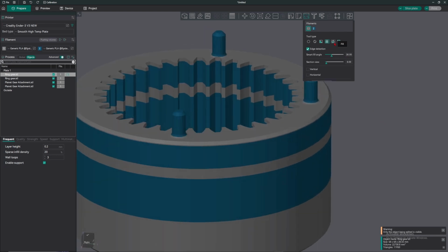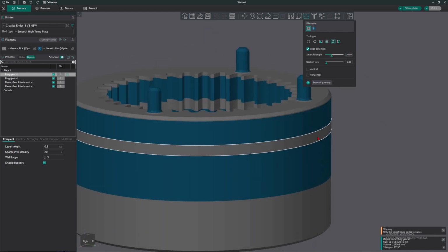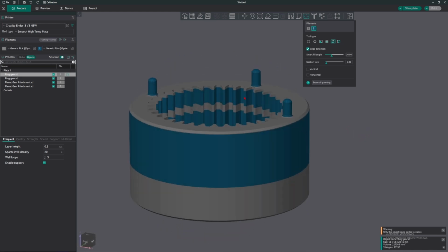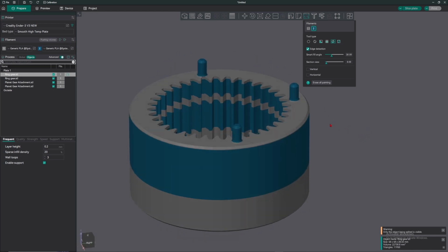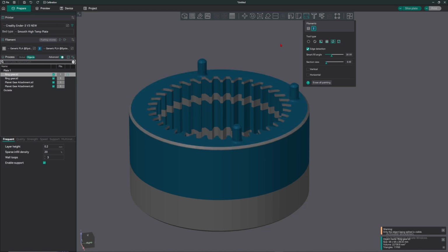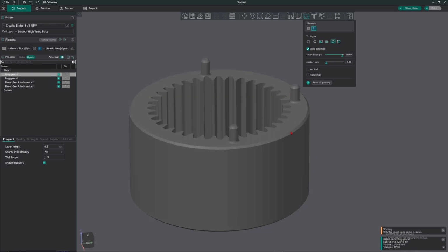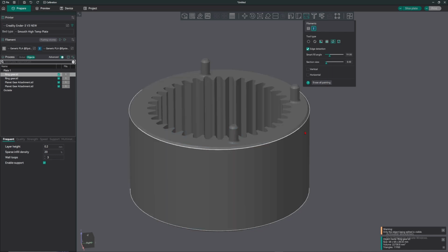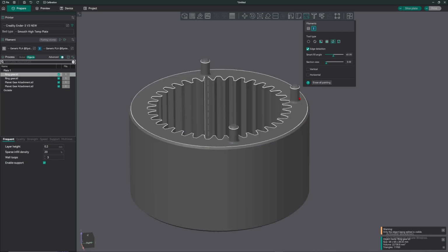The next one is fill. So you can fill in these sections here. You already painted like this, and you just want the section to be filled. So you just clear this, fill, and it's going to fill everything like that. Not the inside though, only the outside. You can see that it has a white highlight there. That's the part that it's going to paint. But if you increase the smart fill angle to 90, it's going to fill lots of stuff. It's going to basically fill almost everything like that. So leave this at around 19 to 30. It will really give you a good angle.